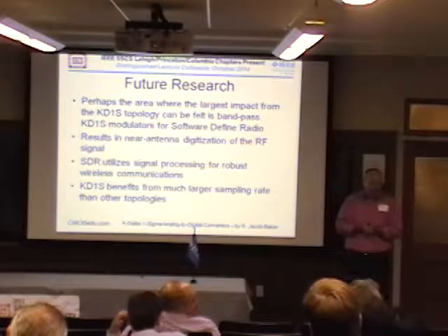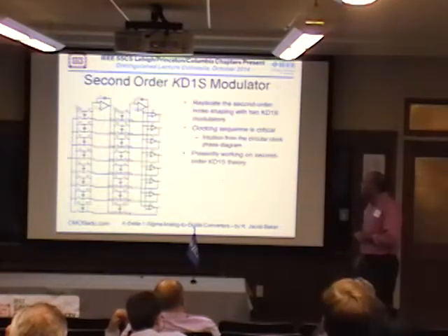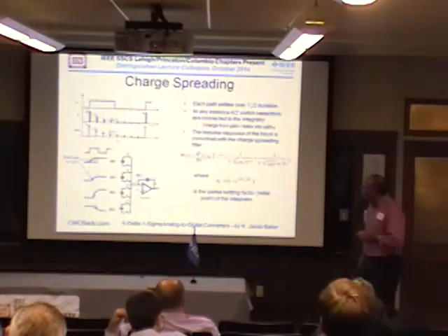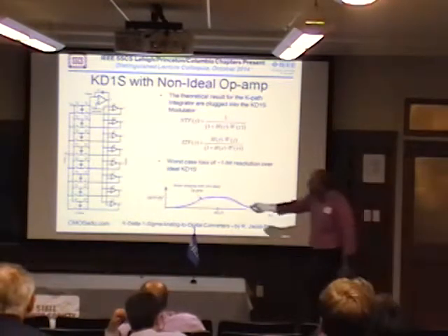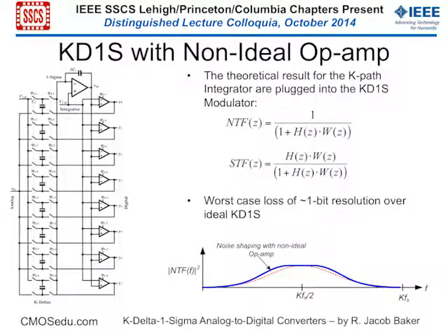Except the capacitor sizes will be different than they would have been anyway. Well, maybe not. Yeah, I guess I'm trying to decide. No, it should be, just think of it this way. If you look at something simpler, each time you sample a signal on here, you get the thermal noise from the switch, and that varies in this random kT over C. Yeah, because that won't be the same size as it would have been.